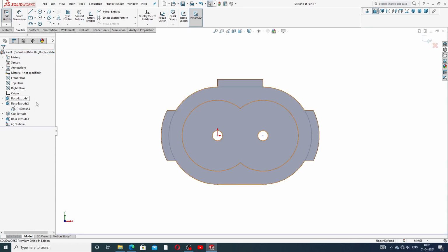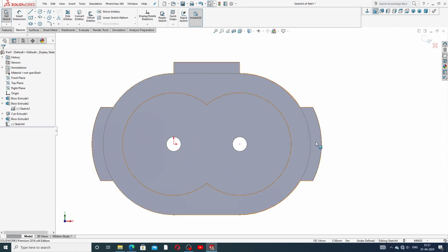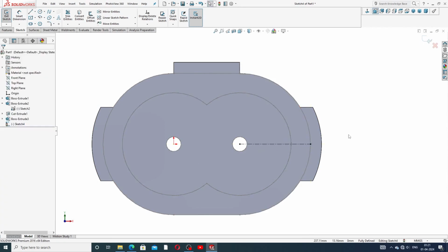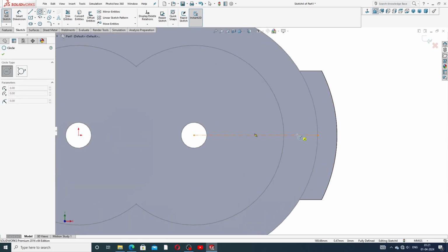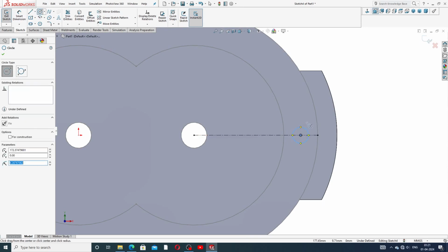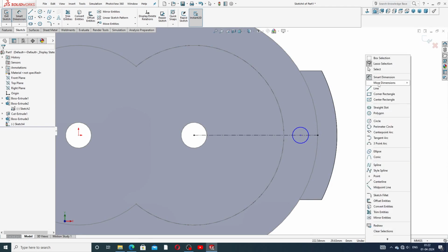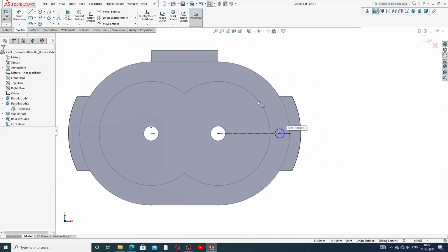The center line is created here, and going to this, connect this to this, and again select this circle, drawing here from this to this, and the diameter is this point to this. Okay, and select this line, and going to convert entities.